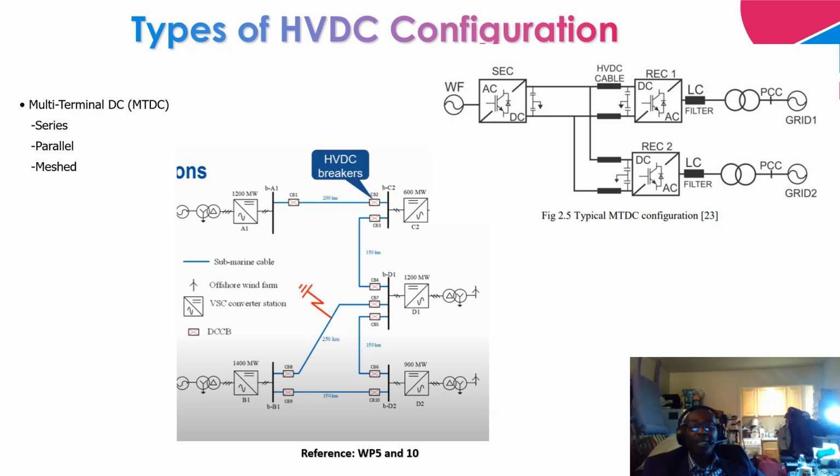This is also located at an onshore substation, right? Okay, so it converts the DC voltage to an AC equivalent, and this is a step-up transformer, a transmission level step-up transformer that steps the voltage from a lower voltage, let's say from 230 kV to 400 kV, the 400 kV transmission level to the AC grid.